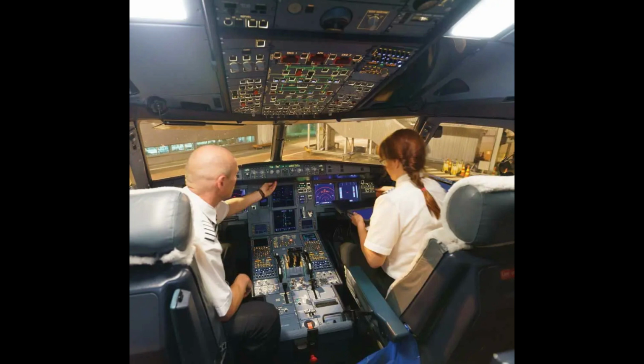2. Distracting tasks/workload. Similarly, the FD/autopilot is used to control basic aircraft movement while the pilot focuses attention on tasks such as reviewing charts, briefing and configuring for an instrument approach, updating weather information, etc. The FD/autopilot can also be a great help in other high workload situations, such as flying in a busy terminal area or executing a missed approach in adverse weather conditions.